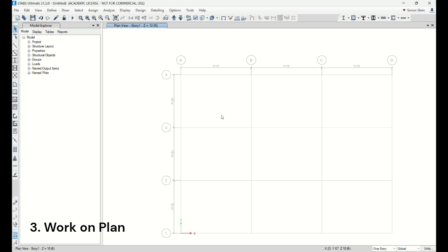All right, so on the plan view, story 1 and below is base. Base is a support foundation level, and story 1 is first floor. So now I'm gonna start with here, right? So material, obviously now what you need to start out is geometry, but maybe want to define the material. Are you working on a steel building or your concrete building or wood building? You need to know what kind of material you're going to use.